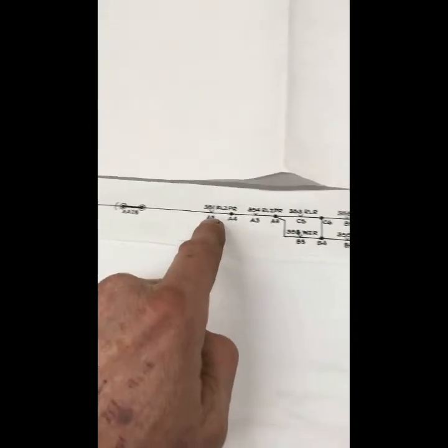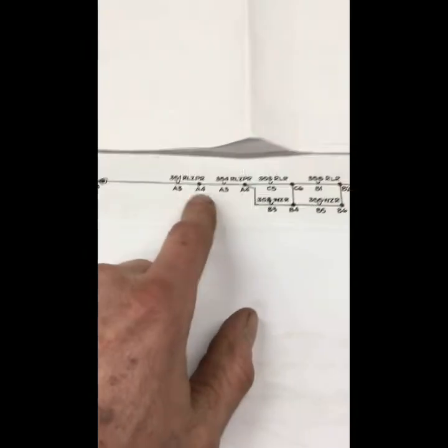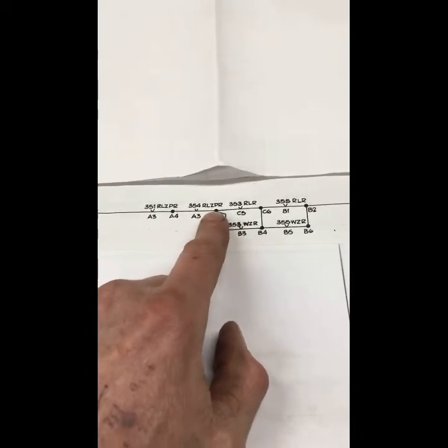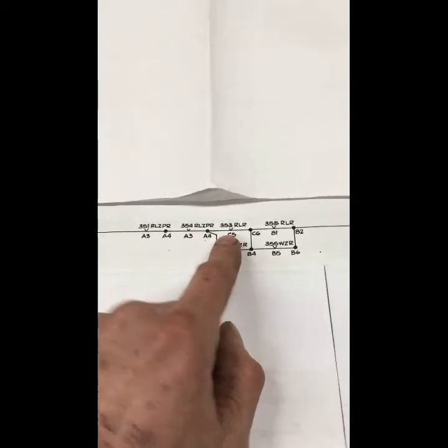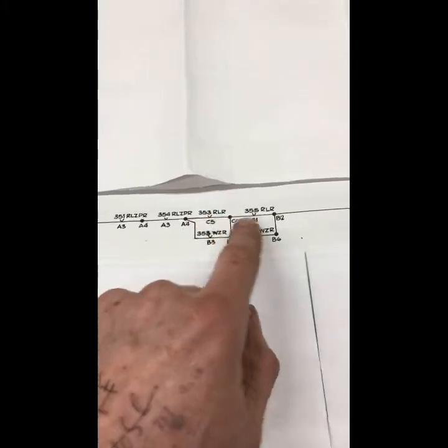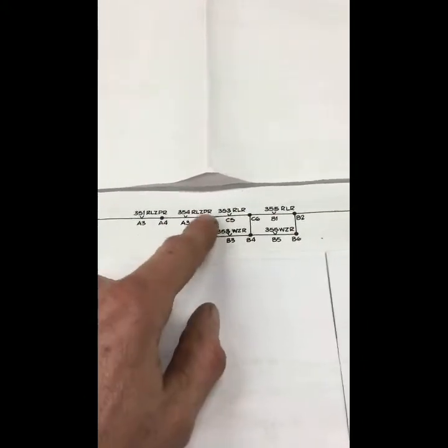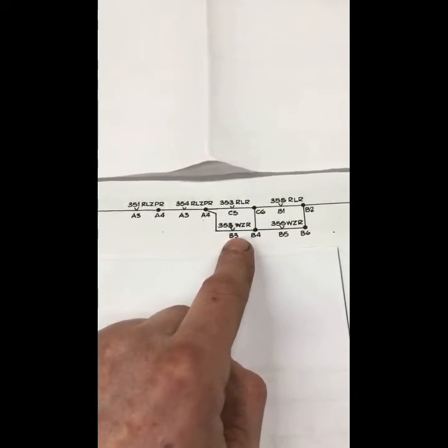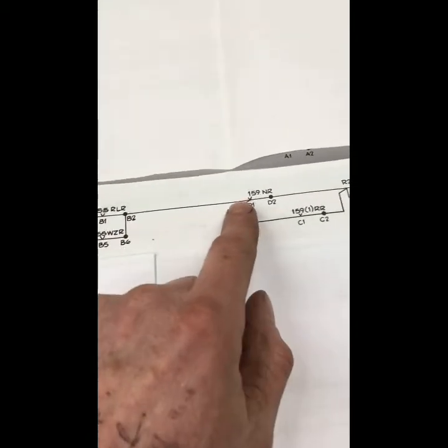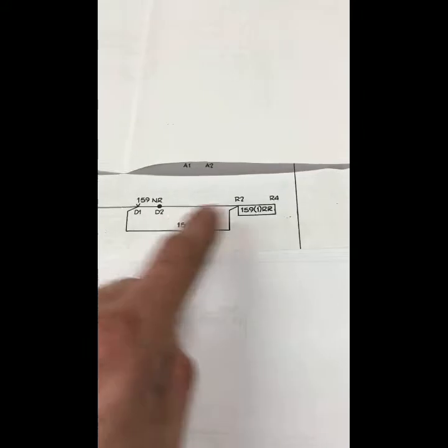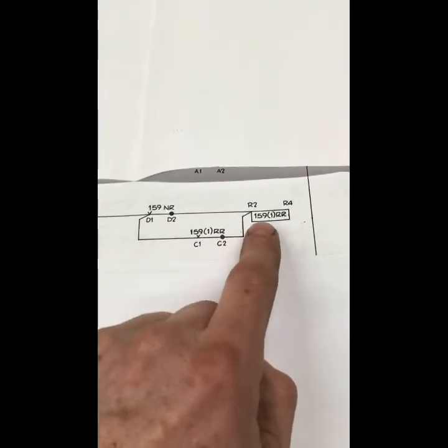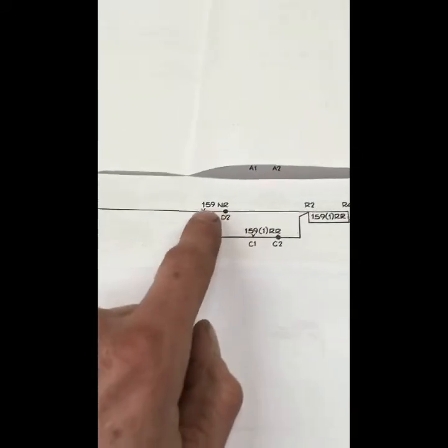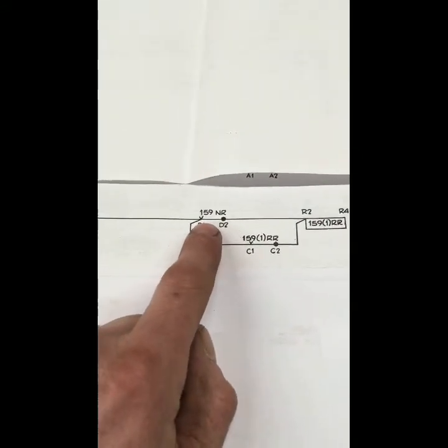Following it along, we go through our point controls and our WZRs. If we've cleared our route for our points to operate, they will be across. If not, through the WZRs, the point available to be called, and that will then allow us to go through. Now this is our cross protection circuit, so if we are clearing our signal route 1, then we have to have our normal relay down.